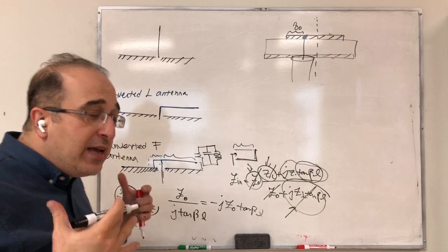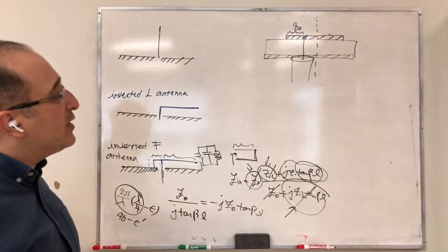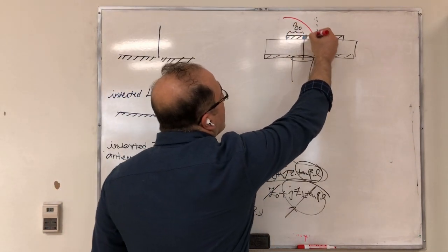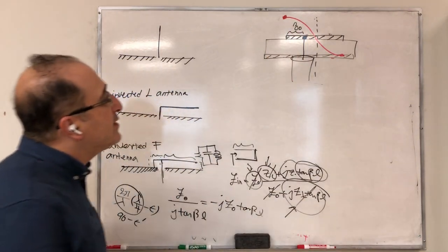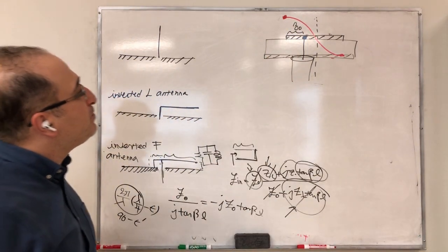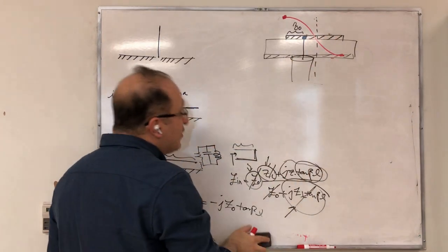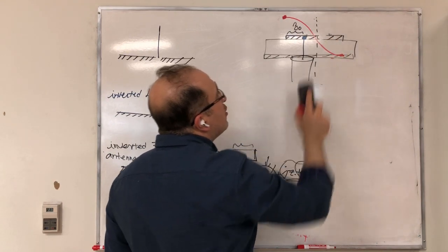So now, based on this excitation, I have my electric field distribution. And again, if I consider my transmission line model, this is the voltage that I'm going to get along the patch. So now, if I want to get rid of half of the patch, I can, but voltage here goes to 0.